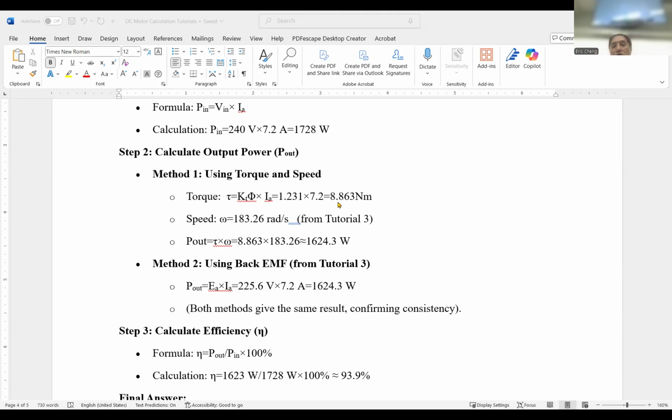So in the whole tutorial here, we are using a chopper to reduce 300 volt to 210 volt. Once the voltage is reduced, then the back EMF voltage also becomes reduced. So we got low voltage, then we have lower speed. So we can actually use the duty ratio to control motor speed, because the input voltage can vary, we can therefore vary the EA. So this input voltage from a DC source or DC power supply, through a duty ratio, we can have low voltage.